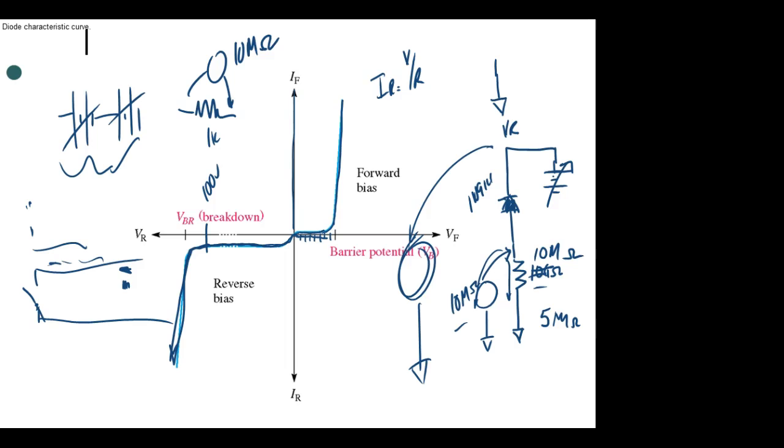When you get into a lot of these high resistance circuits, like some of these communication interfaces here, like this guy, you put a regular meter in there, you're going to affect that circuit. But if you know how it's going to affect it, then you know how to compensate for it, right? Does that make sense? So when we put that 10 mega ohm resistor in there, we'll measure this if y'all want to. But 10 mega ohm will be close enough. We're just not going to use 10.